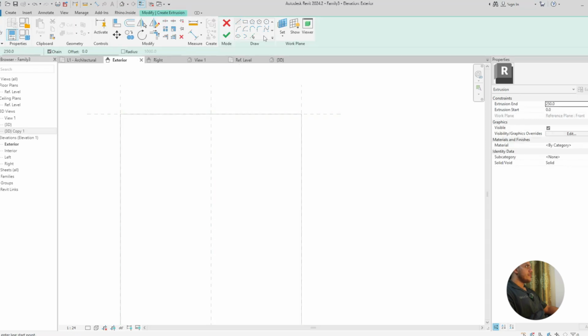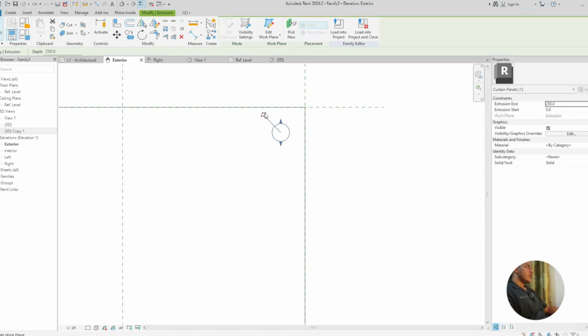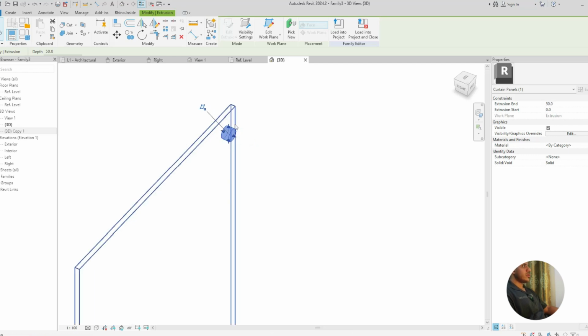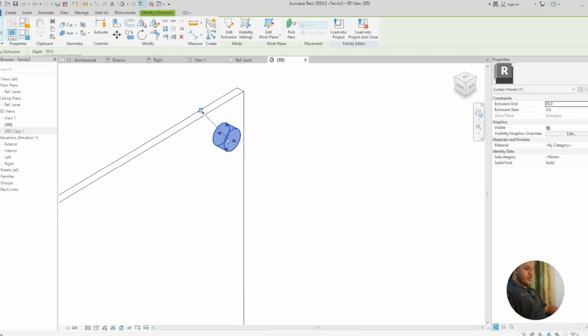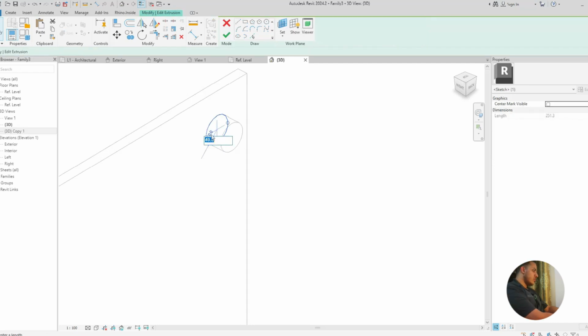and understand the process. So let's first pick plane, circle. Let's make it a 55 centimeter radius, or maybe lower. Okay. Check the 3D always when you're working as a family. Then a good tip: if you want to duplicate this, copy and align to the same place, so you can take it and drag and adjust whatever you want.